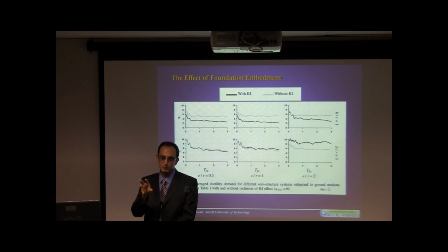But as the input to the system, we can input just the free field motion horizontal, and of course it will rotate and rock. But we can solve the problem subjected to the resulted sway and rocking, which is resulting from the kinematic interaction effect.